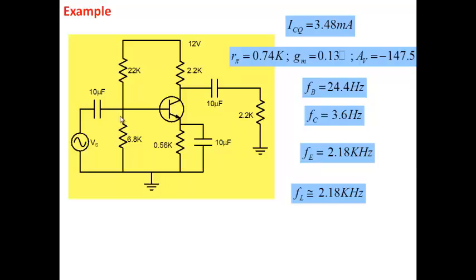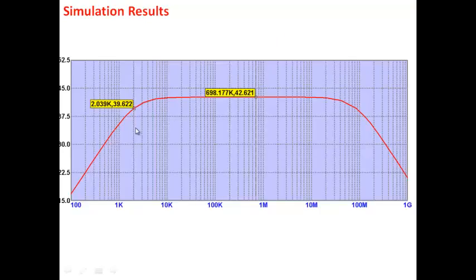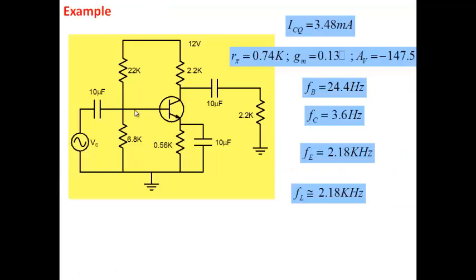It should be less than 1 kilohertz. Looking at this kind of behavior, maybe you'll try 200 hertz or something like that. So you know that I should have my 3 dB frequency at maybe 200 hertz or so. Once you've made that choice, how would you go ahead and choose these capacitor values? Let's focus on this one. What do I have to do?